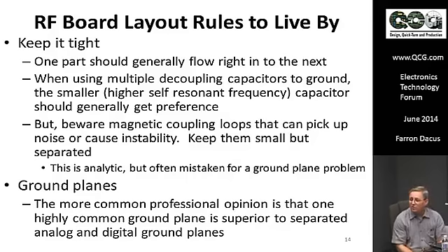And the ground plane you're using for the whole board might not be the one that's appropriate for a certain impedance you want. Like suppose you've got a couple of amplifiers that by their nature are closer to 100 ohms and 50 ohms output. And instead of wasting parts converting them to 50 ohms, maybe you want to run a piece of 100 ohm microstrip at a different distance, different depth from a ground plane you've set up for nominally 50 ohms in other places.